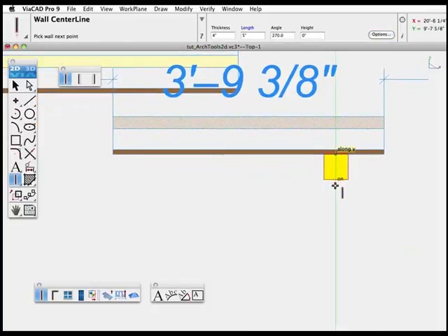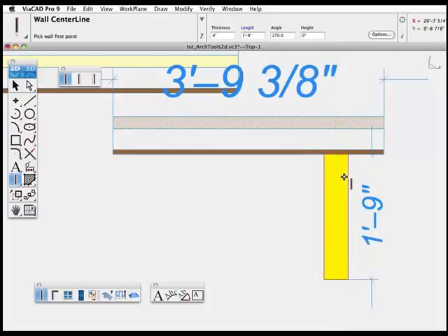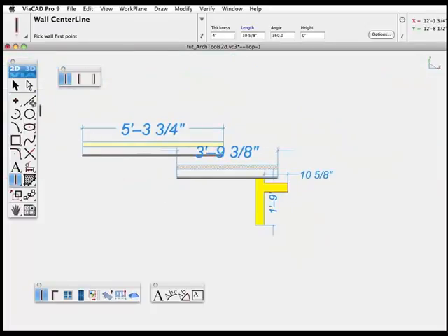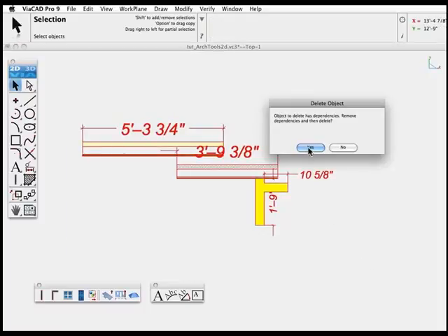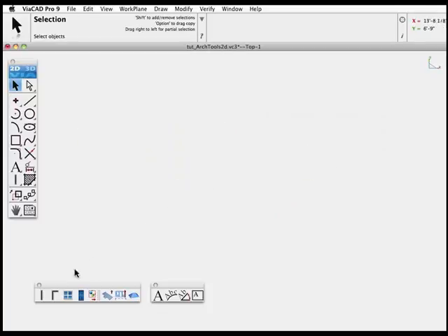And we'll just add one more wall using our other style. Now, in looking at this wall style, you'll notice that it's not symmetric. That means that one side of that wall style is meant to be the outside and the other meant to be the inside.